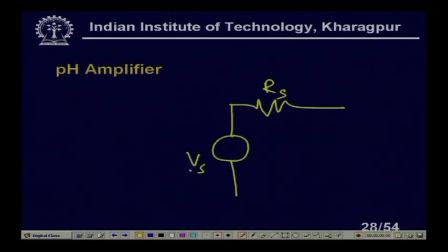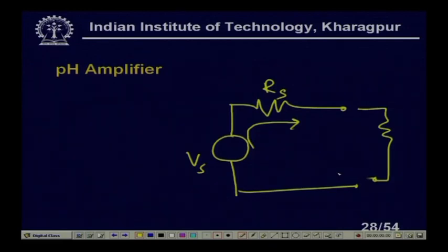If I try to draw some current through this circuit, for example when you measure with some meter that has an input impedance, a current will start to flow. There will be a large drop across this, so I won't get proper measurements.